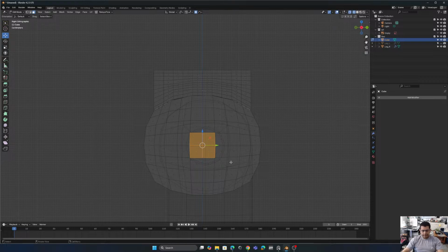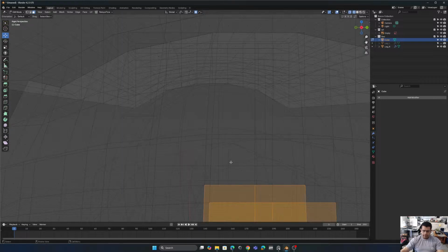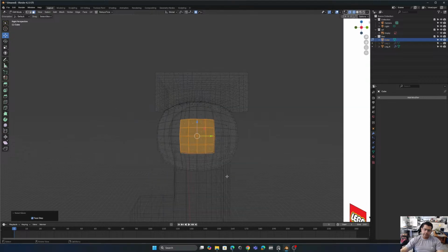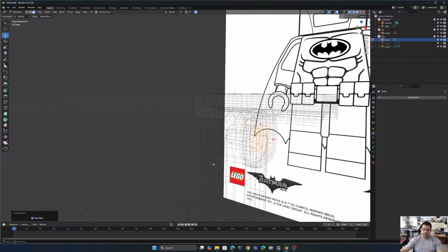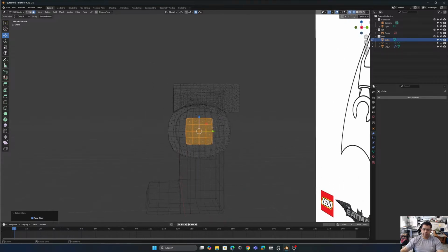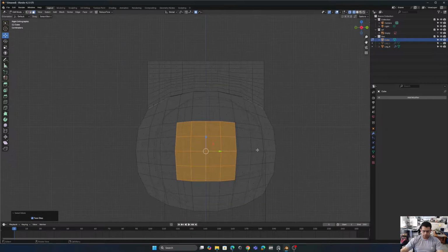If you already select that, you could press Control plus, and you're going to increase the faces that are around the selection that you already made. Same as well, if you press Control minus, you're going to reduce the faces that are selected. So we're going to press Control plus to increase how many faces we have here. We're going to press 3 to have the side view, and then we could make something.